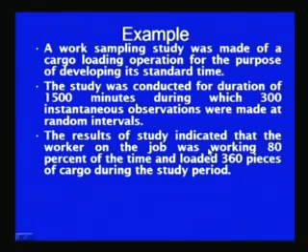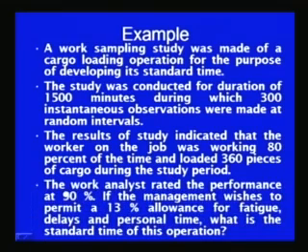The result of the study indicated that the worker on the job was working 80% of the time, and he loaded 360 pieces of the cargo during the study period. The work analyst rated the performance of the worker 90%, and if the management wishes to permit a 13% allowance for fatigue, delay and personal time, then what will be the standard time for this observation.